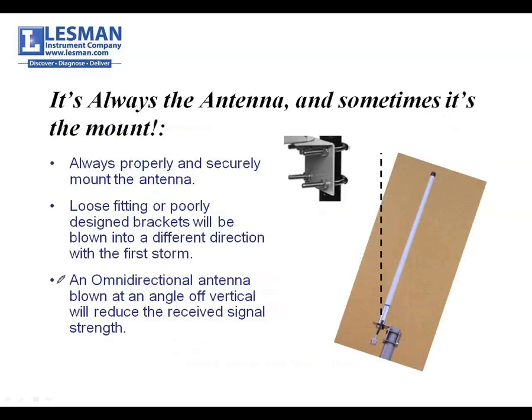Okay? Antennas need to be mounted properly. They need to be mounted in a very sturdy fashion. We actually sell a self-vulcanizing antenna tape that we encourage all connections are wrapped with. The quality of the antenna wire, the quality of the connection, and the quality of the antenna are all very important to long-term reliability and robustness of your environment. A lot of times we'll see antennas that are hanging down or crooked, and that is not a good thing.